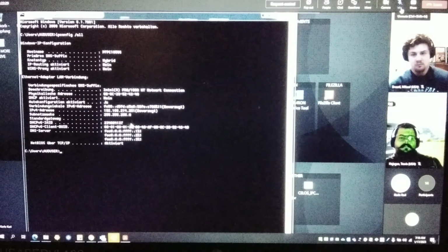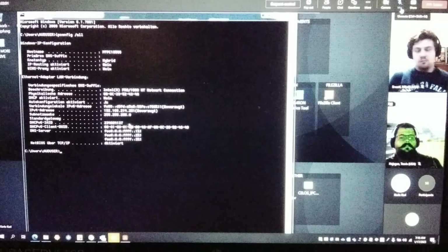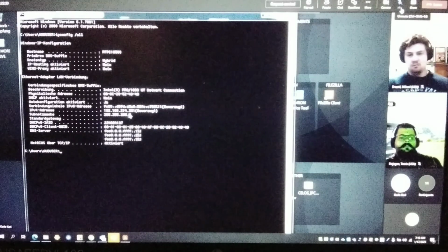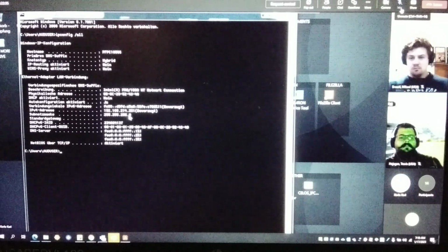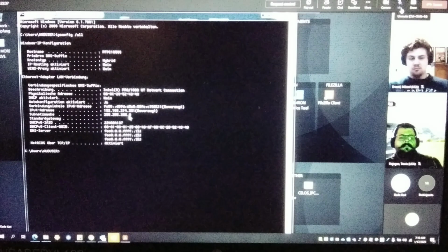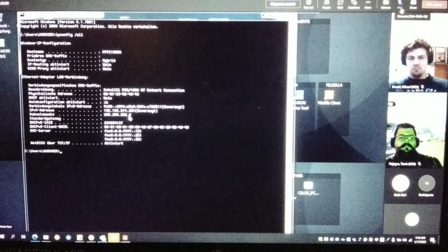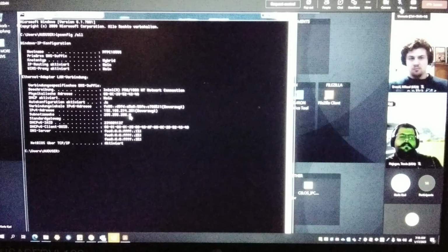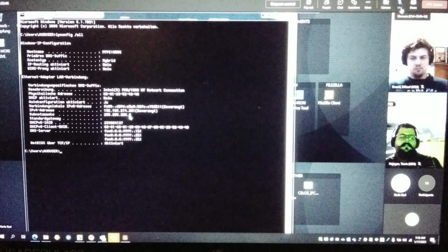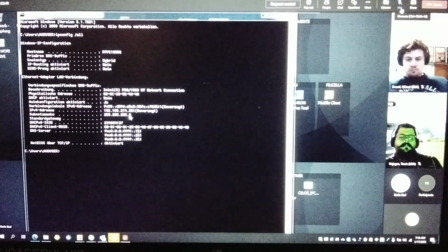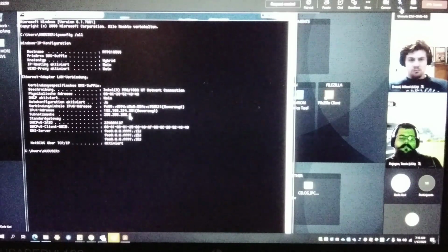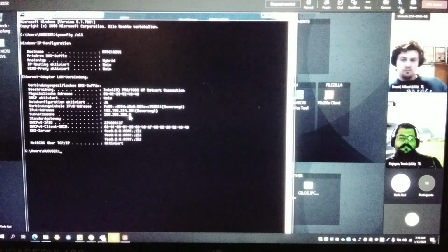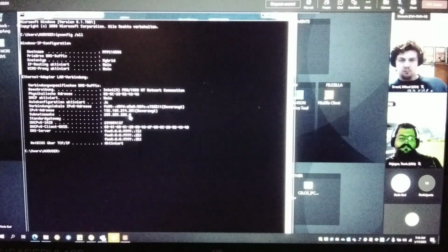Also here we have a condition: the values 1 until 249, including 249, we have to keep for controller components. Why? At the beginning of error debugging, maybe we do not really have an overview which units are assembled on that machine and which IP addresses are really in use.